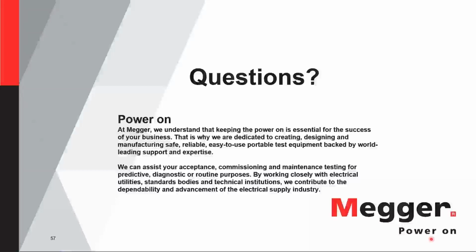A lot of times we don't realize that if there are scratches or any kind of carbon accumulation on the electrodes, that can drastically change your dielectric breakdown voltages. So that's a good question. I would say every 6 months to a year, I would check my electrodes for any kind of scratches that develop over time.